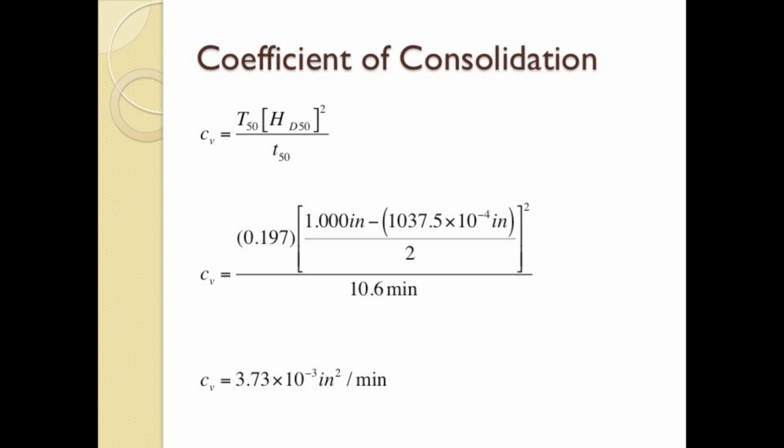Always in the case of the consolidation test, the two-way drainage condition is met. This means that a void in the soil has two paths of travel for expulsion, bottom or top. Therefore, the drainage path is half of the clay layer.